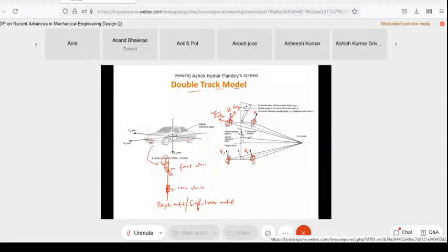After you put all these forces over here, what you do, when you turn the vehicle, you get centrifugal force, right? Centrifugal force will be developed over here, mv square by r of this kind. If velocity v is there, you will have mv square, and r will be from this to this. So under the influence of lateral force, longitudinal force, and this force, we try to understand what will be the turn of your vehicle, how the vehicle will turn.